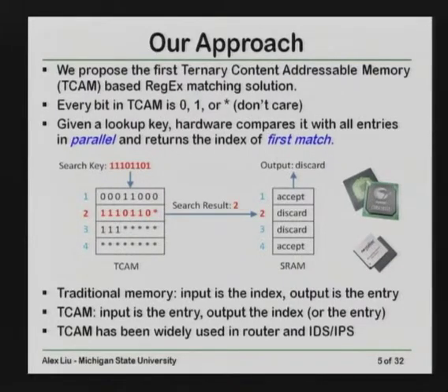In traditional memory, the input is the index, right? You give the index, and the output is the entry. But for this memory, you give the entry, and the output is the index. TCAM chips have been widely used in routers, IDS, IPS, and so on. The most popular use is for packet classification.